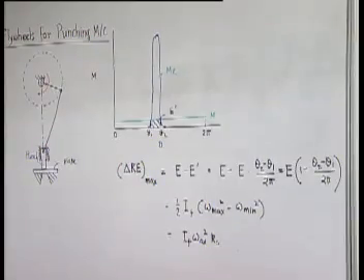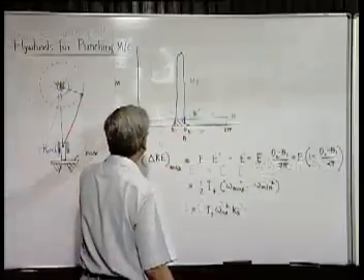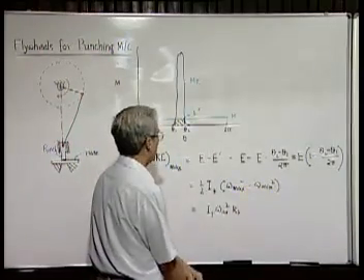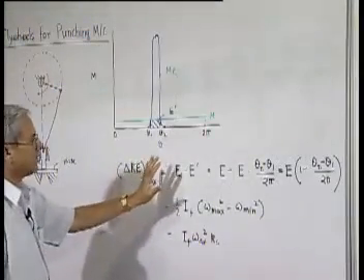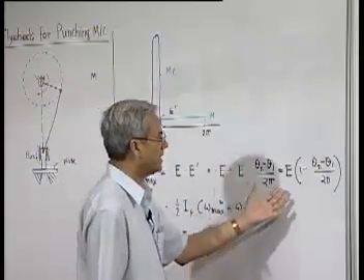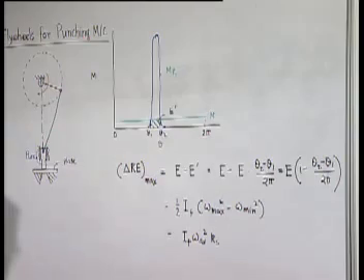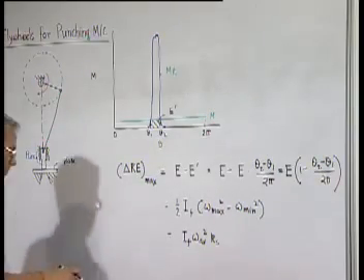and we have seen that this can be written as I F omega average square. So in this case, rather than going into the details of where the intersection points are and finding them in a complicated way, a very approximate method for finding out the fluctuation of energy in case of punching machines can be taken as this. Now let us take up a particular problem.